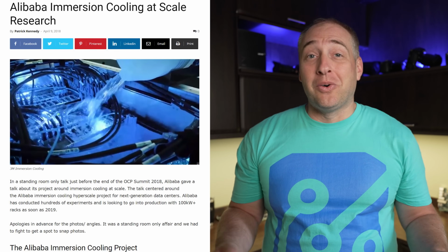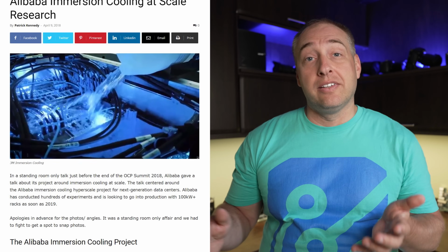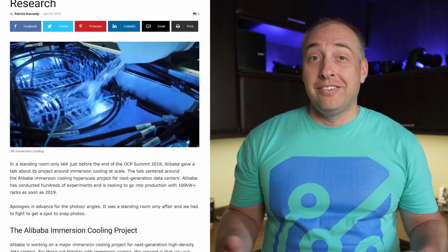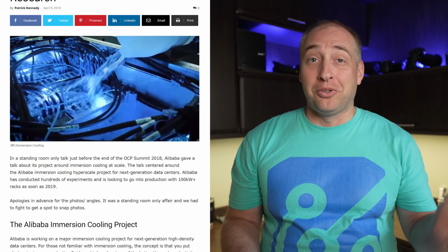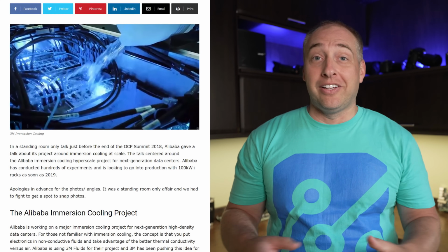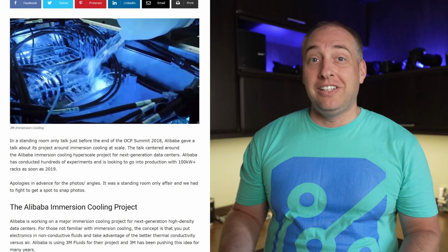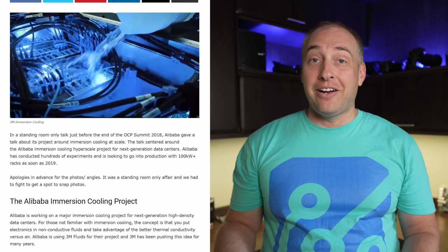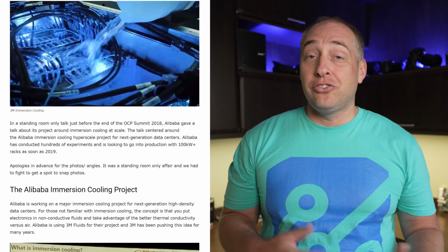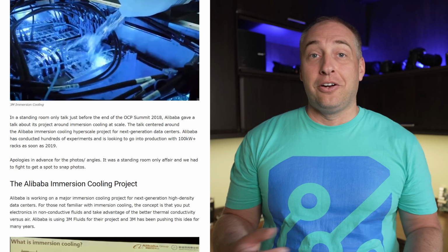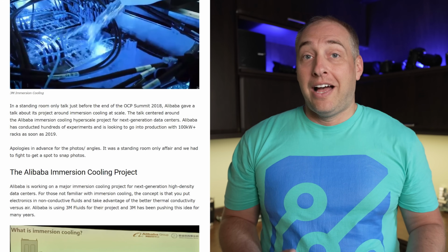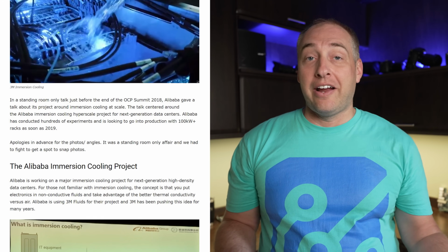And in fact, another really interesting one is that this actually became popular in places like China, where you have large population density at elevation, because your air density changes with elevation, right? When you're, say, on top of a mountain, you're not gonna have the same density of air that you have at sea level, and that means that you have less dense fluid, which means that you can't transfer as much heat in air, and so a data center that's air-cooled at elevation is not as efficient as it would be at sea level. So the immersion cooling solves that problem, because you have a fluid that has a higher density and allows you to take more heat out. And so that was actually a reason that in China this became a, I guess, preferred solution for some of the higher elevation data centers.